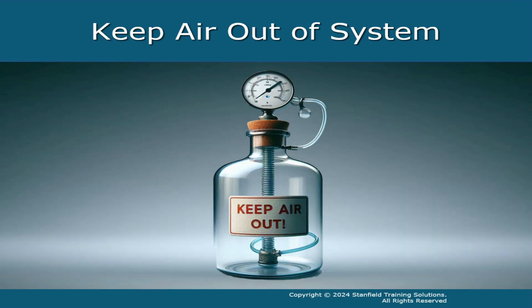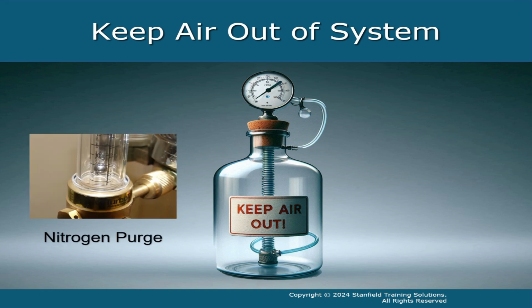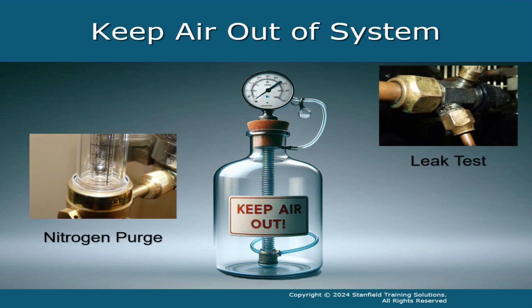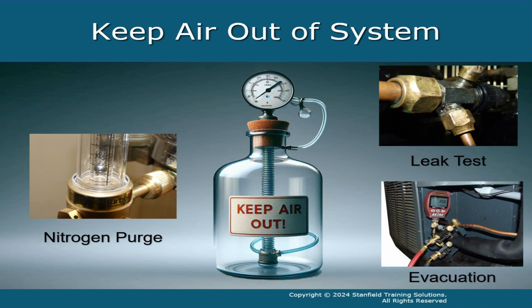We can keep air out of the system by purging lines with nitrogen during brazing, testing for leaks after installation or repair, and evacuating systems before opening charging valves or adding refrigerant.